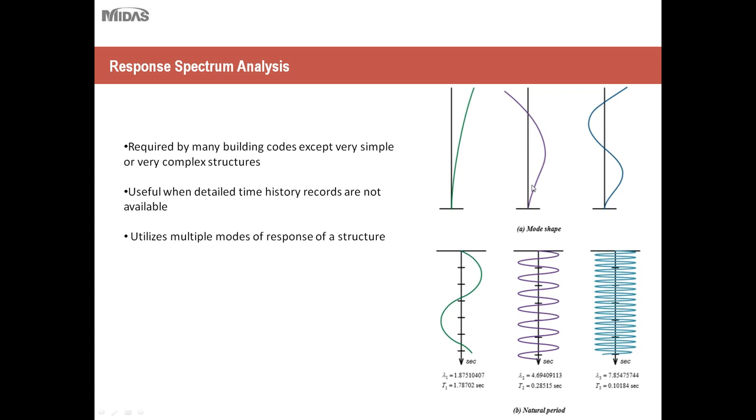Some of you are probably wondering what these pictures represent. When you're doing a response spectrum analysis, essentially you'll have several modes that you'll be studying. Each of these pictures below represents a different period of the wave. For example, let's say the earthquake just starts, and this is what the vibration looks like, and this would be the mode associated with it. However, when the earthquake picks up, the frequency or the intensity and strength of it might increase, and then you would have a different modal shape.